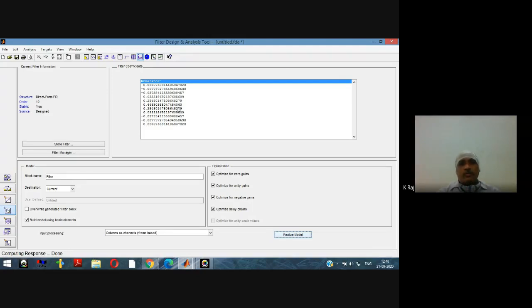of approximation for that method. For example, if we have selected FIR, then in the case of FIR there are so many methods, and we have selected the windowing method. And even in the windowing method, there are different windows that are used for the purpose of designing the filter. Then we have selected a particular window, that is the Hamming window. And then we will select the order.